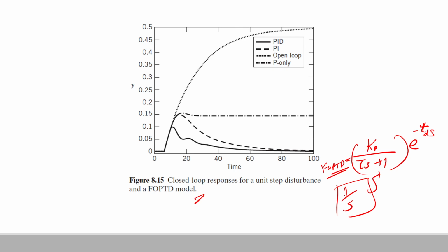what kind of characteristic curves the PID controller or the PI controller gives is shown in this graph. This corresponds to the simple open loop process. This is the response of a first order system, and since we have the delay term, we can see the delay present over here. This will be tau d. Now we can take a look at the P controller. Over here you can see it will not reach the set point, the P controller would never be able to reach the set point.